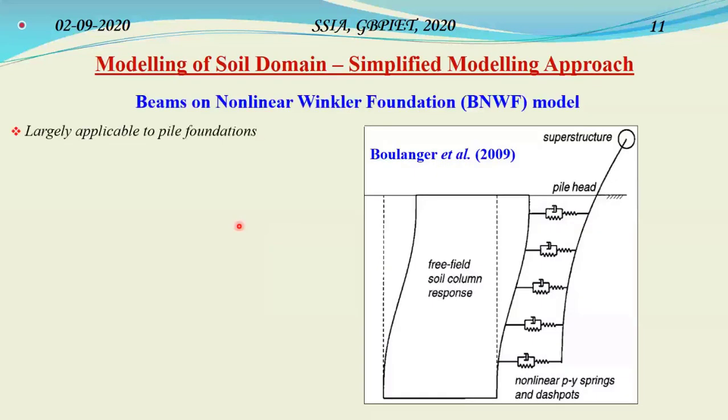When coming to pile foundations, one of the very popular methods of modeling the soil domain and the soil structure interaction is through beams on nonlinear Winkler foundation, or BNWF model. You can see in this particular figure, the pile is represented by this curvilinear portion. The pile supports a superstructure.